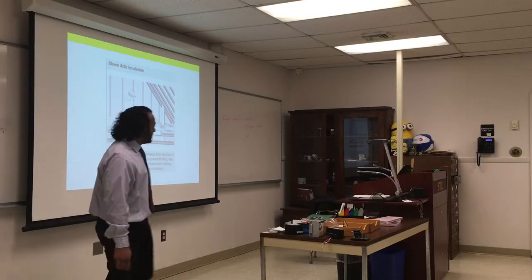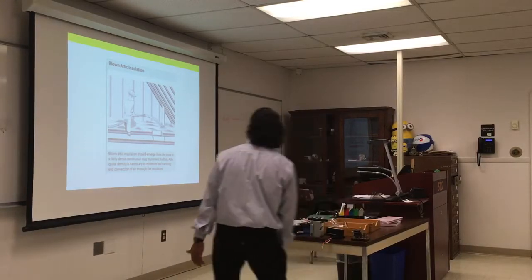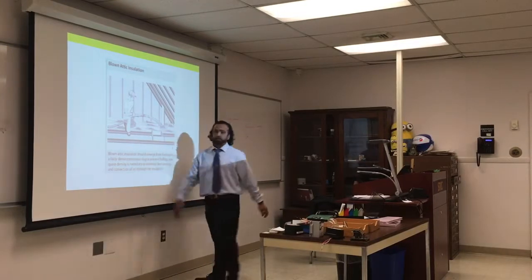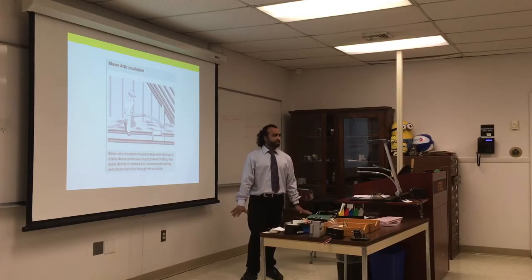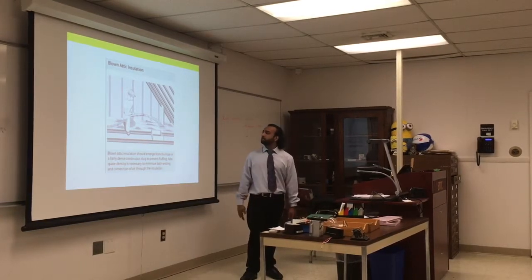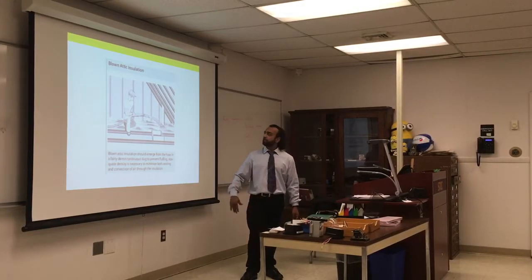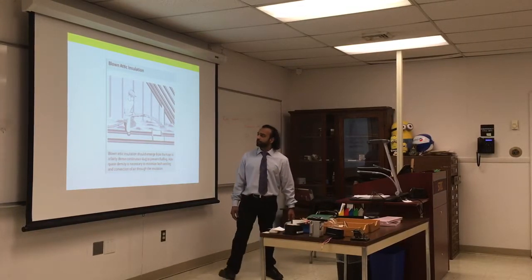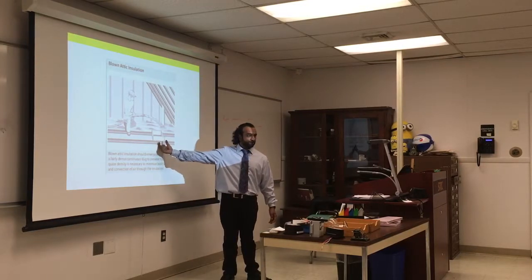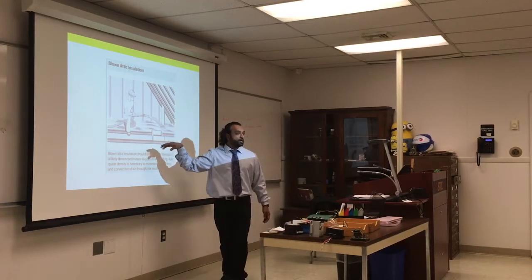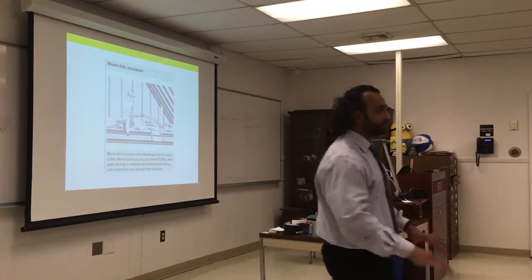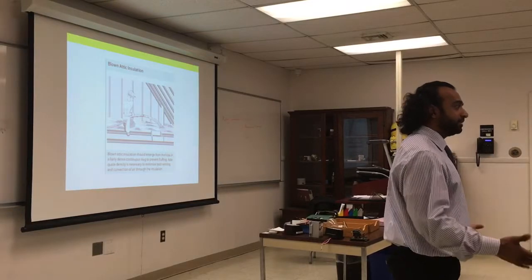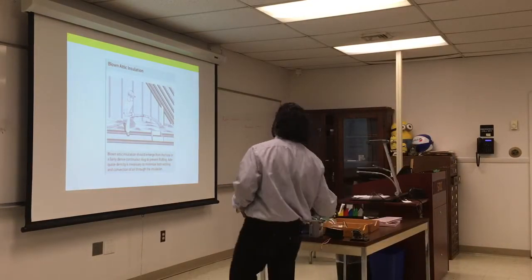So this is how we go on filling cavities for the attic. I have a video that shows you how to do it and how you calculate how much insulation you put. You wait for it to settle, measure the cavity, and add some more, then you cover it up. If you're not using the attic, usually you only leave one place where you can come in on a walkway. You don't want to walk on the insulation unless you put some plywood on it, otherwise you will compress it. And if it's compressed, it's not going to give you the right insulation.